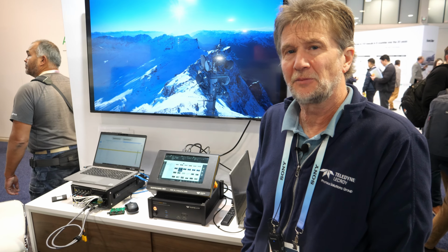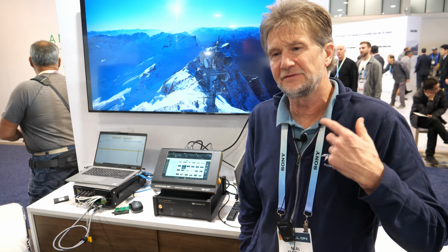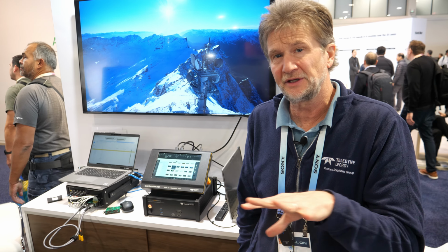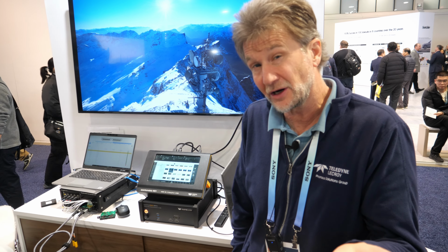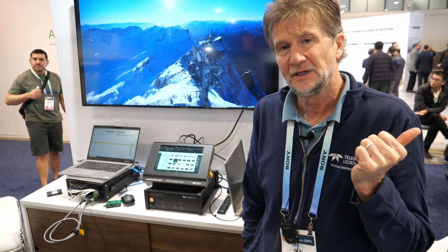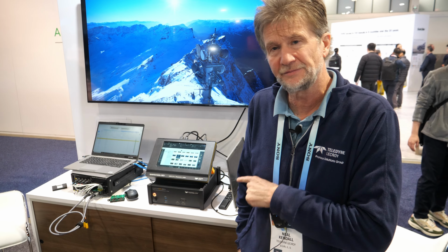You can view it all in our protocol analyzer: the guard band, preamble, data island, the high-speed pixel data, the audio data that's embedded in the blanking, and so forth. There's also the eARC data that goes out in the opposite direction of an HDMI cable for audio to go out to a soundbar. We can show all that as well.